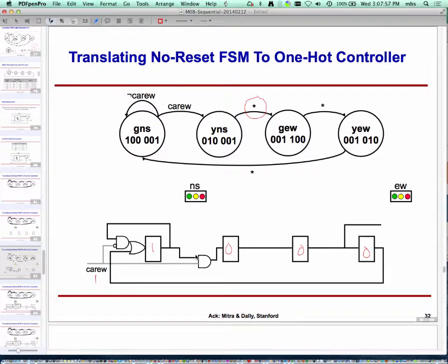So what would be the input of the second flip-flop? Anyone? So input of the second flip-flop would be 1 and 1, which is 1. And therefore, at the next clock tick, this 0 will become 1. This 0, because it picks up the 0 out here, goes to 0. This 0 becomes 0. And finally out here, I have a 0.